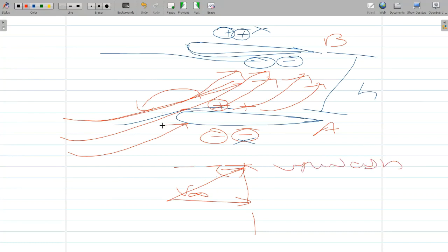So for both these airfoils, the free stream is coming at it in a curved manner because of this pressure difference that is existing in this location and this location. Because of the curving, if initially the free stream was coming like this, it gets an added on velocity component in this way, and the resultant is in this way. So this is basically like an increase in the angle of attack.